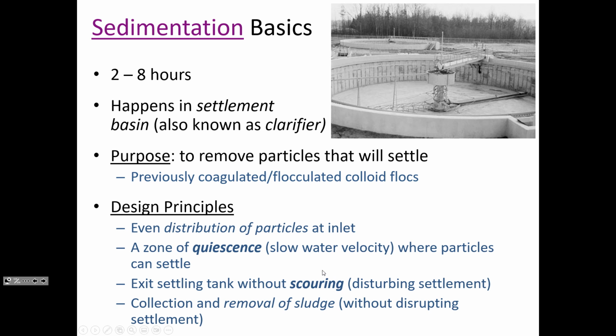Getting out of the tank without scour, and then some way, you can see here is a scraper at the bottom of the tank. It's almost like a squeegee. We need to have that moving at the bottom of the tank without disturbing the settlement that occurs above it. So as you might expect, this wiper at the bottom of the tank rotates pretty slowly, because if it's going around in circles really fast, then the particles wouldn't settle in the first place.